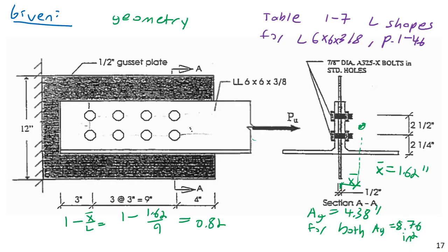So back here, again, block shear rupture, we don't need to worry about that because the magical genie took care of that. And in terms of the fixed connection, when we actually design things in the real world, we have to start worrying about whether the weld is strong enough to hold the gusset plate to the fixed connection, and whether the fixed connection, whatever that thing is, a column or a beam, is strong enough to withstand this loading.